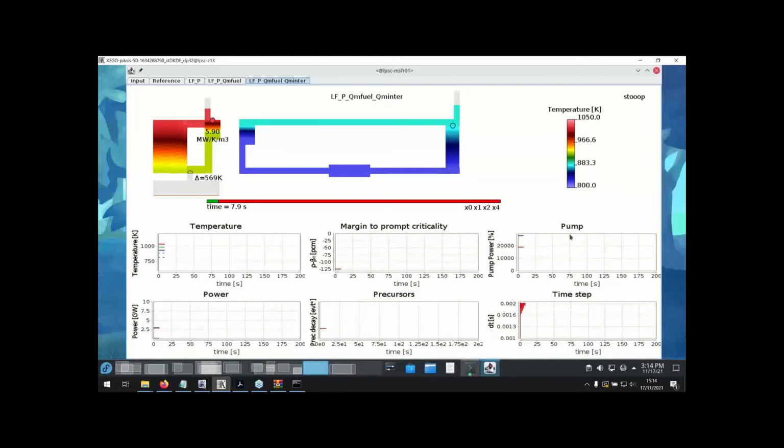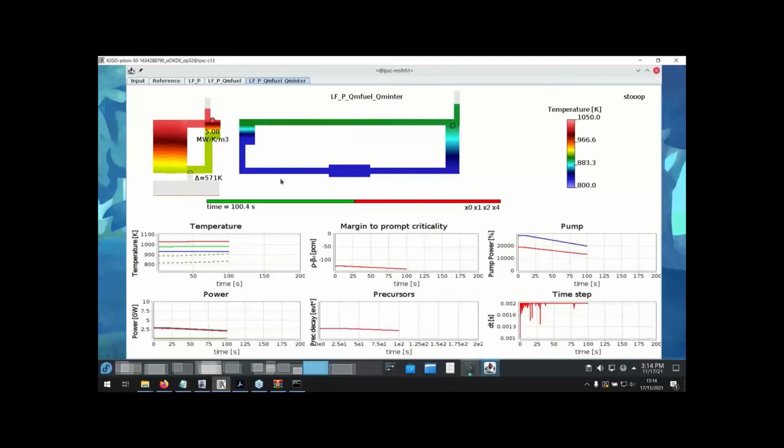You will see here that both flow rates are decreasing in accordance with the scenario we set. And you will see that we should keep the same delta T in temperatures. We might have just a slight increase in temperature in the intermediate circuit because of the transient. There is a delay in the circulation of the fluid inside the loops, but otherwise the variation in temperature is reasonable.